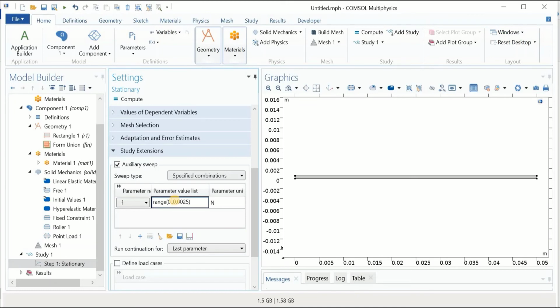For example, I can use 0.0005, right? Or even smaller, let's use 0.001. I think that should be fine for the force range. Like I said, it's a very slender rubber-like material, which means that we need a tiny force to make the buckle. We can also find that based on the calculations, right?